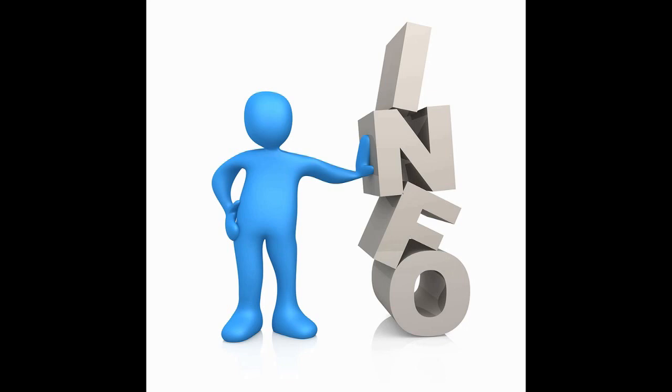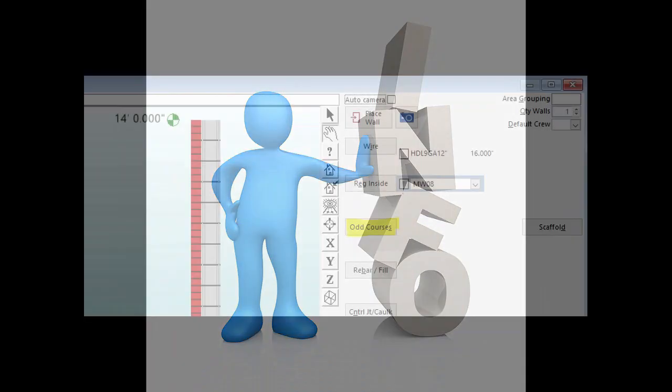Note: the odd course button on the right side of the screen will default to entering odd courses in the interior width of the wall, and the left-hand side will default to entering in the exterior width. However, you will have the option to change the width from the odd course screen.